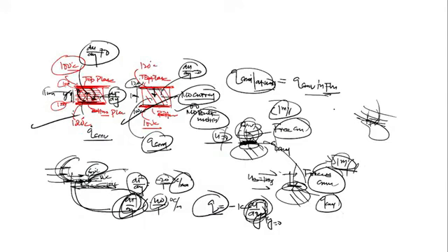And consequently the temperature gradient at the wall increases. It means the rate of heat transfer via conduction at the wall increases. Whenever I'm talking about conduction, this should be at the wall. The rate of conduction at the wall increases, and that rate of heat transfer through conduction at the wall is equal to the rate of heat transfer by convection in the rest of the fluid, which will also increase, and then the time to cool it will decrease. Is this clear? Any doubt you have, you can ask me.